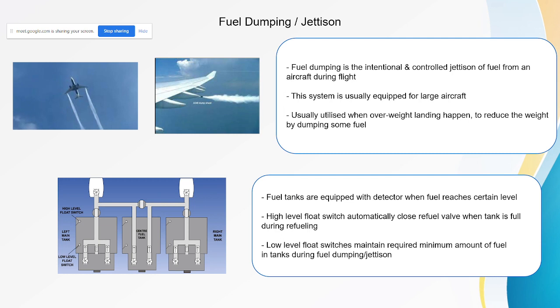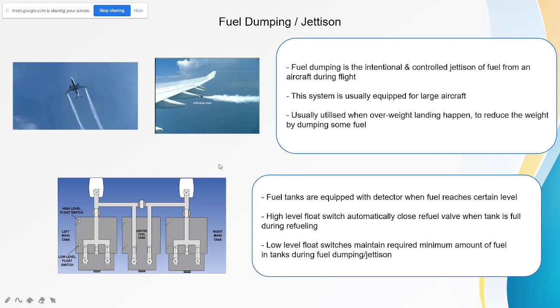So normally when we use fuel dumping or jettison, Nazrul, when do we use this system to dump the fuel? Why do we need to dump the fuel? Because normally the fuel dumping will be switched on if the aircraft wants to land, in order to overcome an overweight landing. Yes. When do we do that?